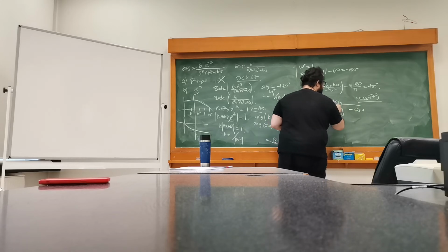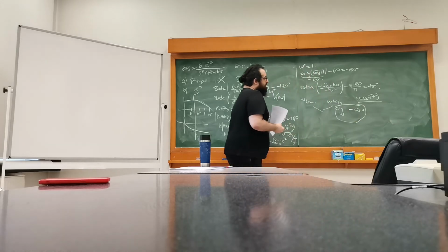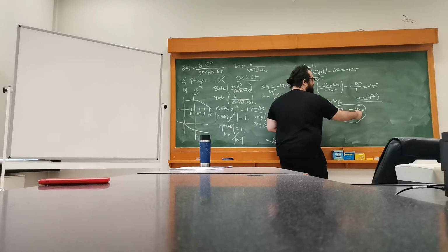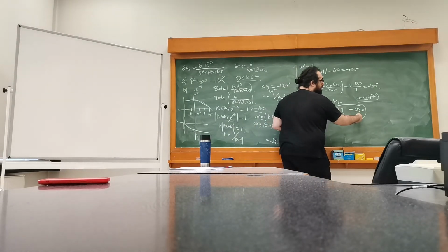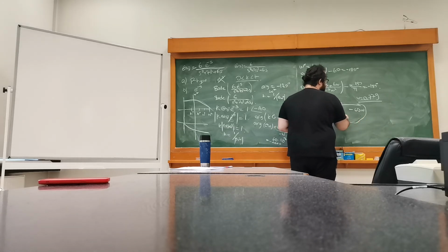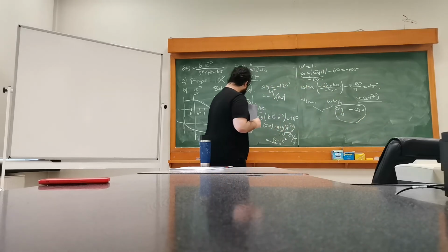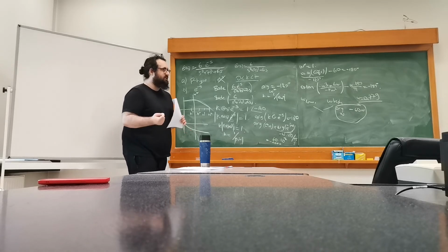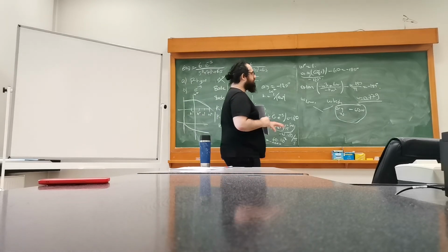So I'm trying to use this here. Omega should not be really huge. Omega cannot exceed 3 here because it will be minus 180 degrees on its own. But the system itself has also a certain phase value. Therefore, I have to track that and combine these two pieces of information in order to approximate what omega is.